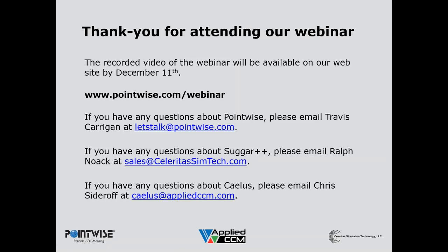As you saw, in Pointwise we pulled up a cut plane and we were looking at fringes. You could also look at donors and see what blocks donors are coming from for your overset grid assembly. You can also look at not only fringes like we did, but also your orphans, try to identify where those are and mitigate those problems. So there are a lot of different metrics that you can look at in Pointwise for your grid.